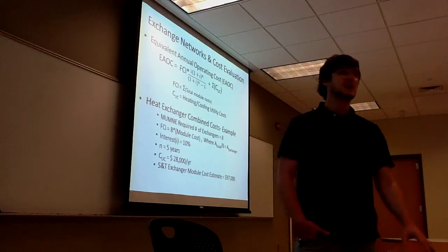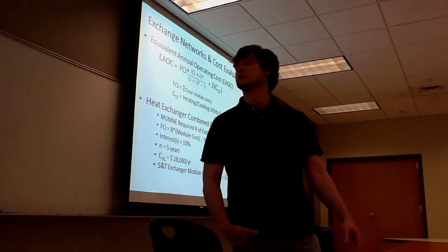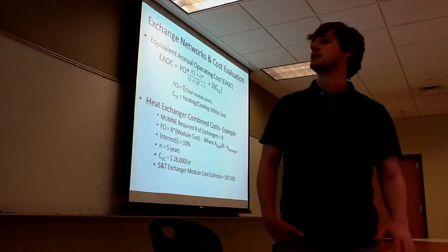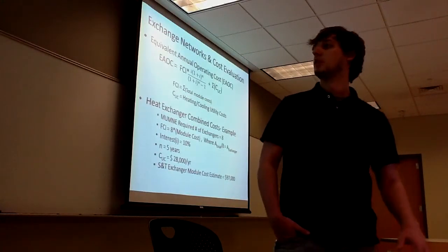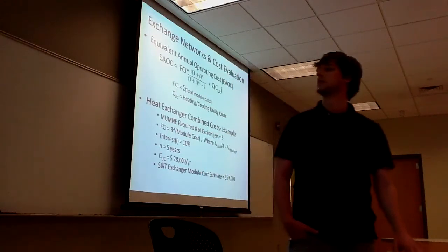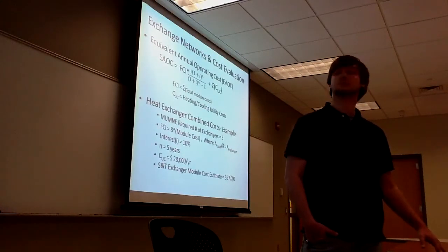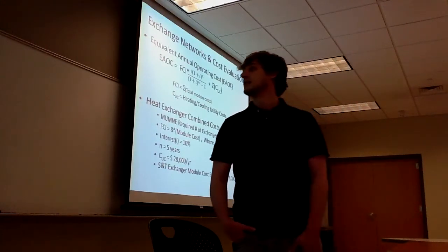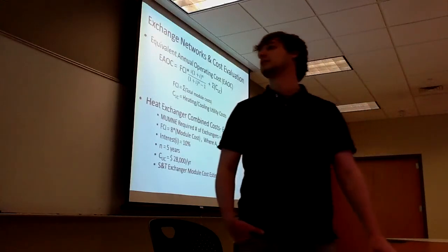analysis. And for instance, if you did your analysis just like Rebecca did, you came up with 8. In the text, they say the best way to cover everything is to use the total area and divide it by your number of exchangers, which is going to give the area of one exchanger. And then from that area, that one exchanger, you're going to use the module cost estimate, which again is from parametric optimization, and use that as an estimate for your exchanger module cost.